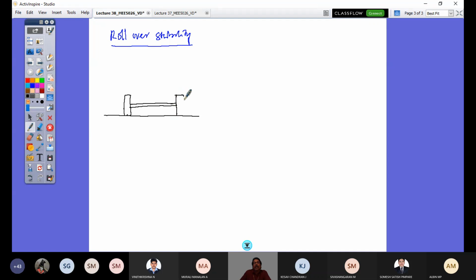So now again I'm taking the YZ plane through CG location, like that you can consider. So the left side two wheels are taken together, right side two wheels are taken together, and you define your roll center point with this kind of representation. So this point is your roll center, and your entire vehicle sits on this.